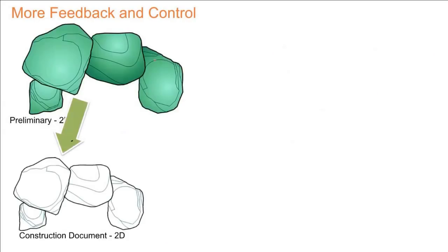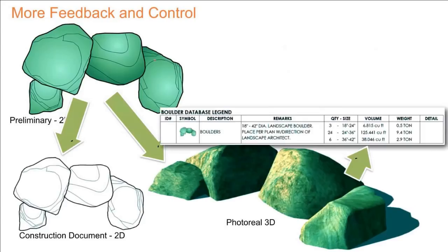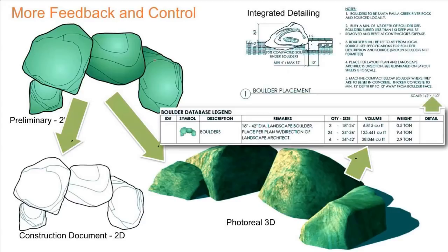We use it for boulders. We have 2D, 3D representations of boulders. We can schedule that into both quantities, and you can see here we quantify our boulders in tonnage, so we can get cubic footage of actual modeled boulders that we can then use to estimate how much they're going to weigh for cost estimating purposes and for quantifying in bids. And then linking that directly to detailing that shows up on our plans.